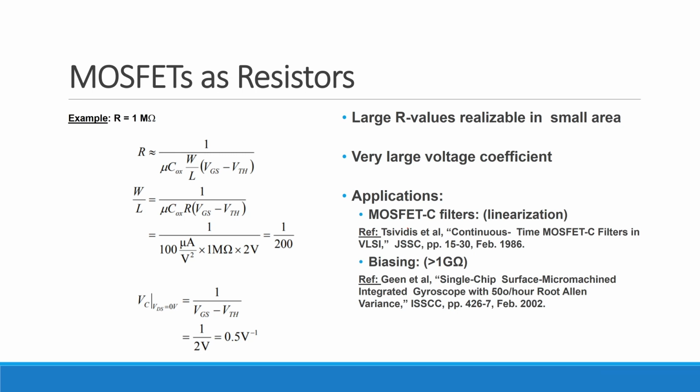Sometimes you just want a big resistance, and if it's even varying by a factor of 10, as long as it's big enough, that's kind of okay, right? So anybody have an idea where something like that might be okay to deal with? It varies by a factor of 10, but you just want it to be big. Where's a circuit that might help you with? The noise in the bias circuit too. Okay, yeah, bias circuits, right?